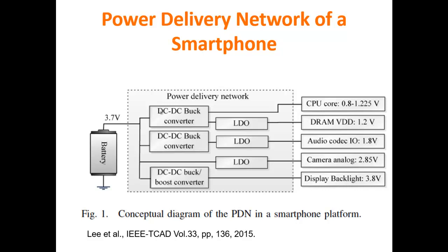So, for example, by reducing the supply voltage from 1.2 to 0.8, one is able to reduce the power consumption by half, all else being equal. So, at the same clock frequency, at the same computational performance of the CPU. And this is done dynamically. The operating system basically negotiates with the power management system what is the proper supply voltage for the CPU. And this is one issue.